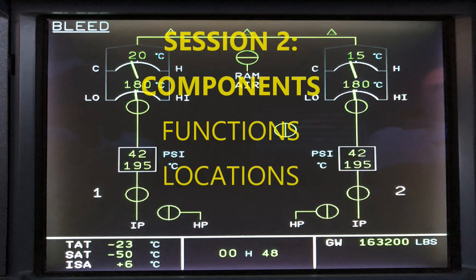Okay. And on this particular one, there's an additional function, and as far as indications showing on the display, it's going to give a wing anti-ice fault on the Ecam. So you don't have that on the other one, the pressure transducer for bleed transfer, but the bleed regulated pressure transducer will give a wing anti-ice inop Ecam status on there if, again, there's an out of range pressure.